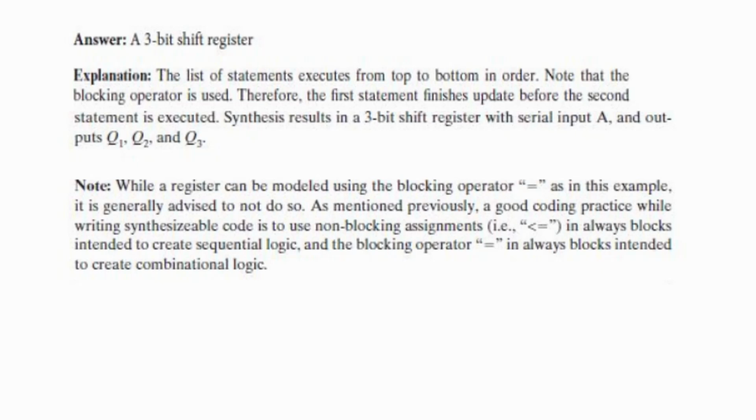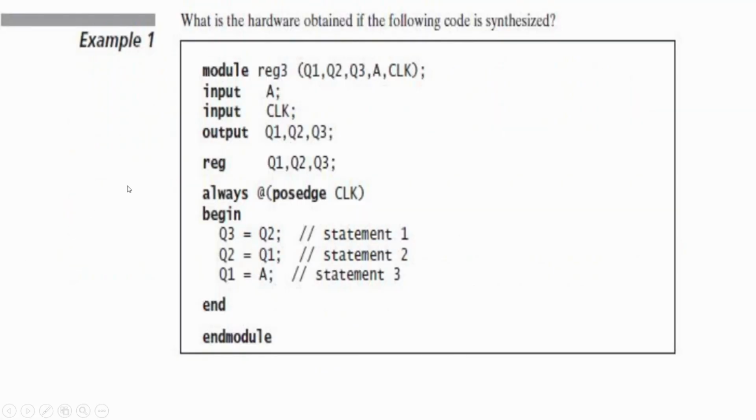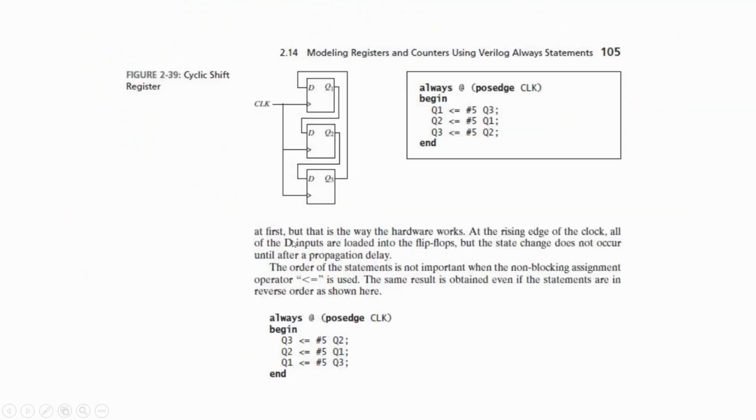As mentioned previously, in the earlier example we used the non-blocking operator, the less than or equal to sign, and it is a good coding practice to use non-blocking assignment operators while writing synthesizable code, in always blocks.